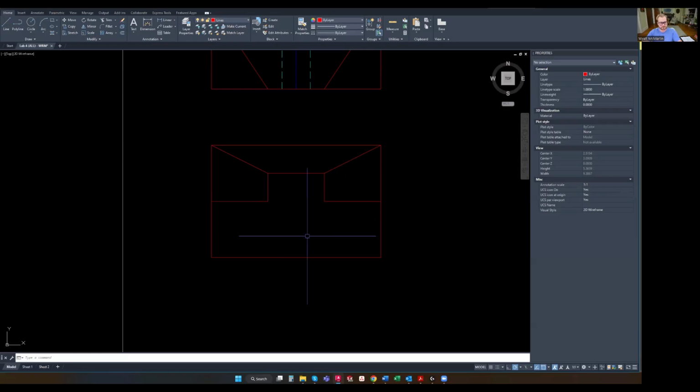And last but not least, let's grab our circle tool. You can grab your circle diameter tool up here in the toolbar. Alternatively, as usual, you can type C, enter. In this case, hover over the bottom midpoint, drag it straight up, and type 0.5 to create the base point of that circle at 0.5 displaced from the bottom midpoint.